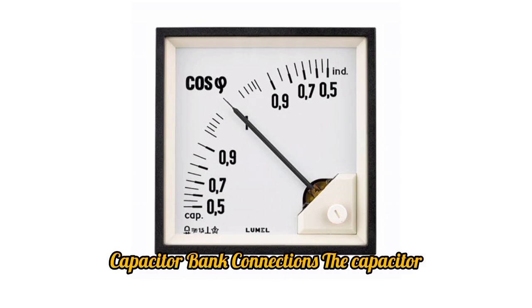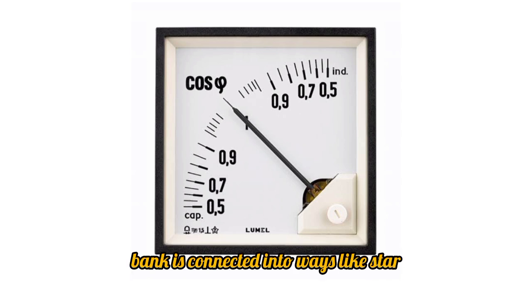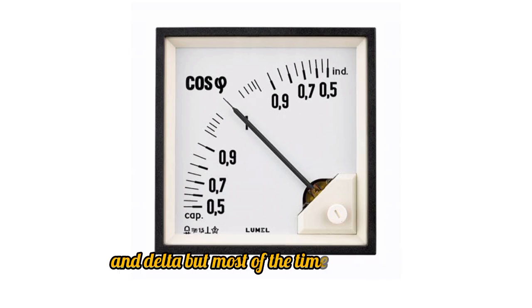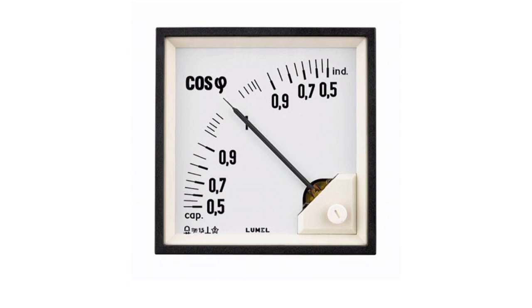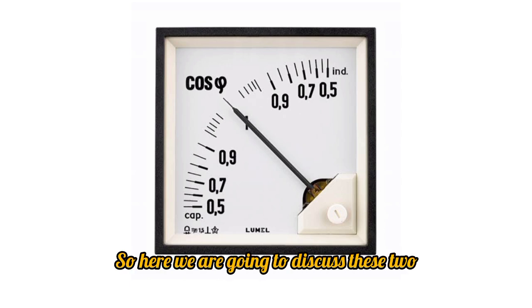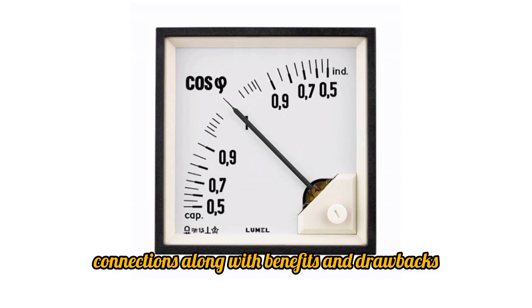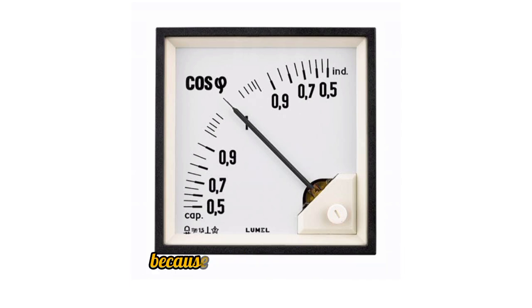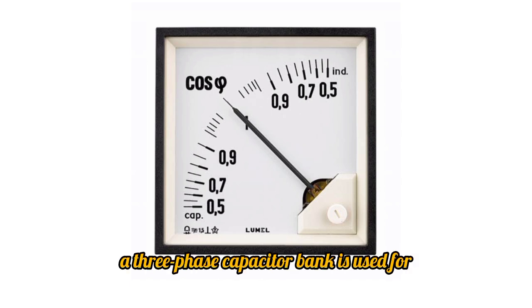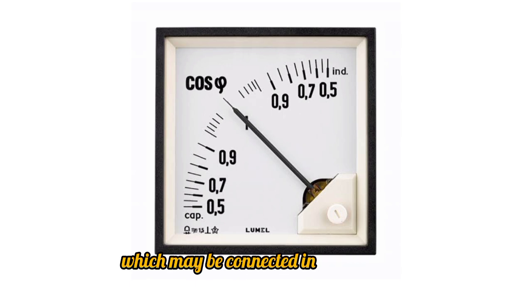Capacitor bank connections. The capacitor bank is connected in two ways, star and delta, but most of the time delta is used. So there is a bit of confusion about which connection is better for a bank. Here we are going to discuss these two connections along with their benefits and drawbacks. The main application is power factor correction, because in a three-phase system, a three-phase capacitor bank is used for power factor correction, which may be connected in star or delta.